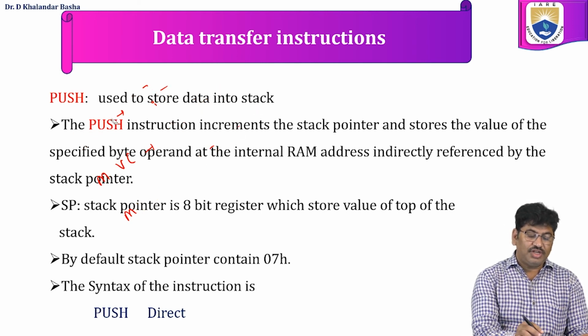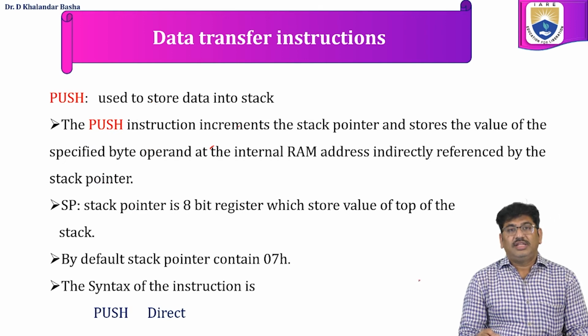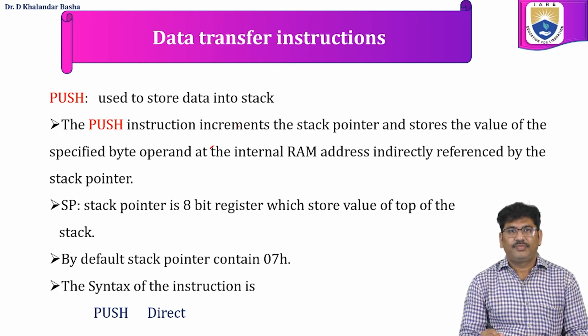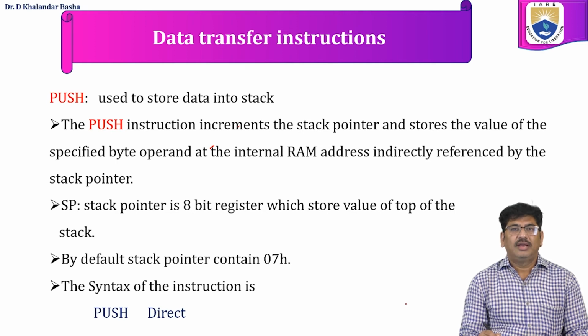The next instruction is the push instruction. This instruction is used to store data onto the top of the stack. The push instruction increments the stack pointer and stores the value of the specified byte operand at the internal RAM address indirectly referred to by the stack pointer.